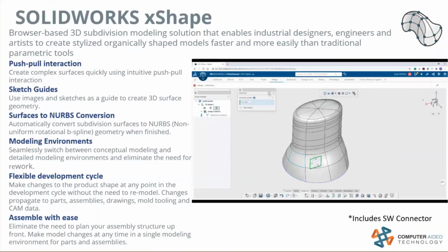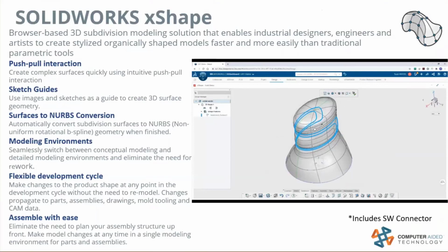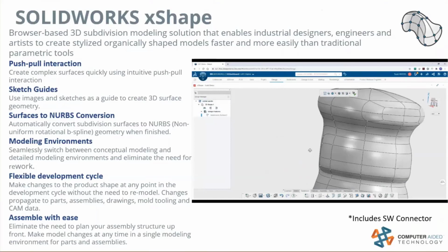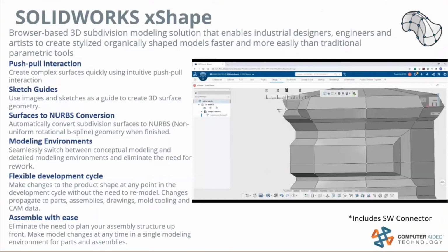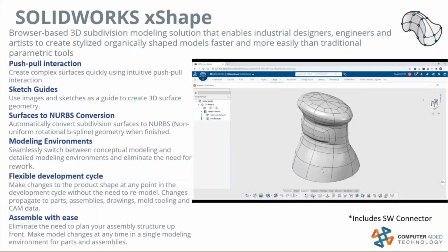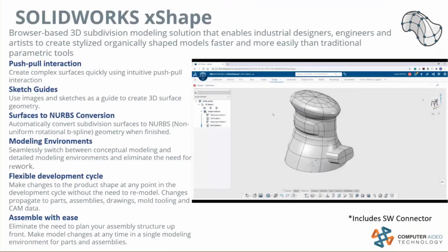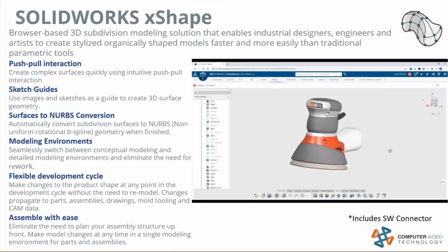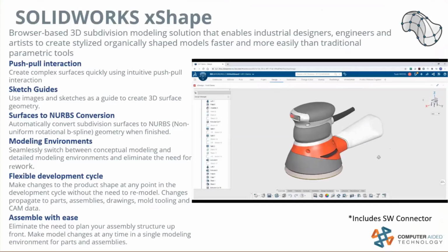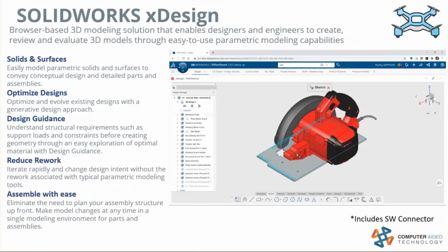Now, Todd and I have both used these subdivision type modeling tools in the past, and they're really nice, but one of the problems was the resultant file was usually an STL mesh file, which wasn't very usable for us as designers inside of SOLIDWORKS or other CAD tools. Here, what it's actually doing is giving us CAD models immediately that we can export and take right into SOLIDWORKS, and split, and add ribs, reinforcement bosses and screw holes, and actually make a real model out of it. So this is a pretty amazing tool. Yeah, definitely functionality that's not available in traditional SOLIDWORKS.